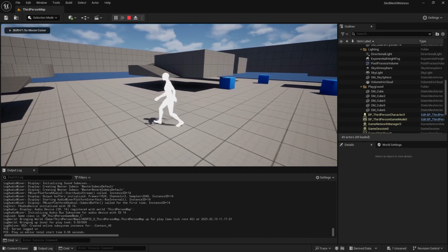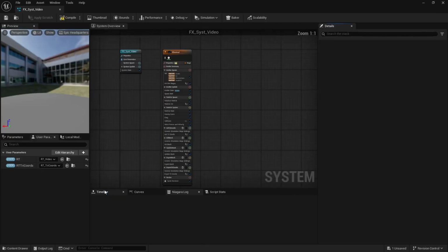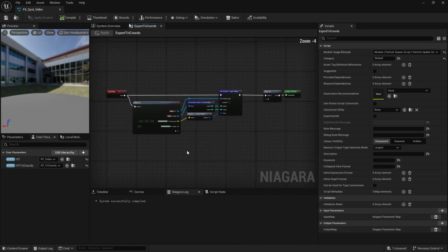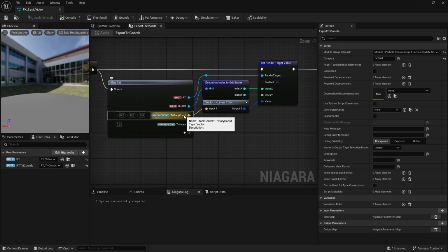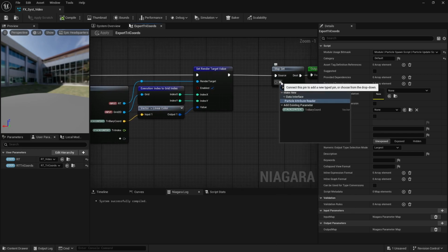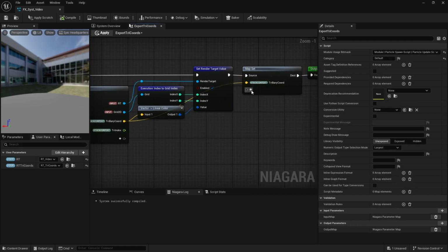And it seems like I broke everything. Weird, huh? Well, I did this on purpose. This isn't very intuitive, but it's something I wanted to explain. See, this simulation stage iterates on the grid 2D, okay? This means that internally a buffer is created, a duplicate of that grid 2D, if you will. So you can both get and set the attributes of the grid at the same time. Which means the grid 2D is cleared of all attributes, so I need to carry them over. So carry the barycentric vector, and the triangle index integer as a float as well.